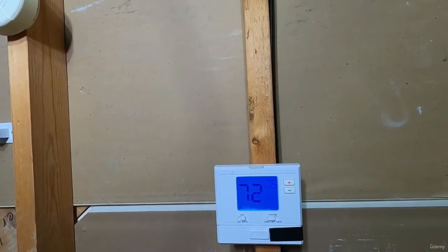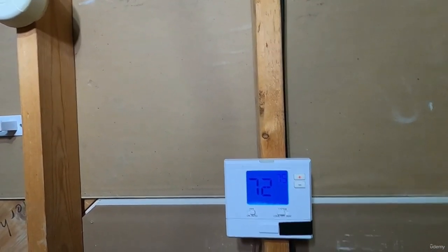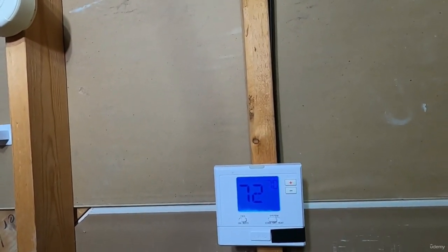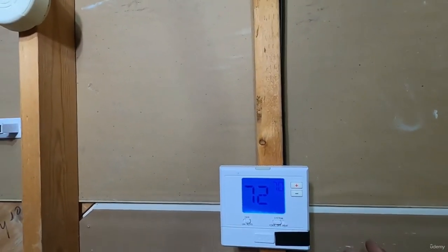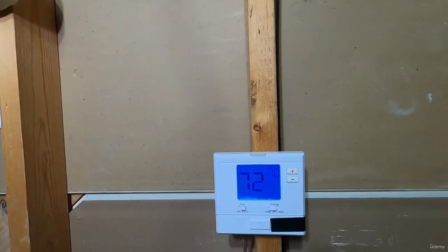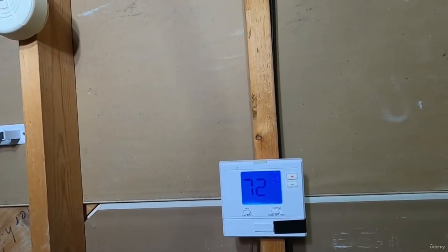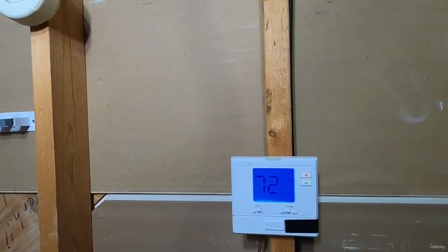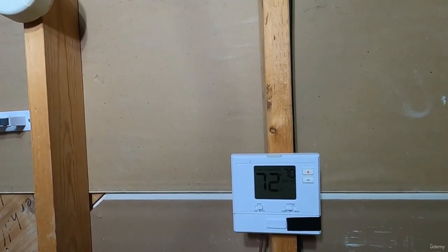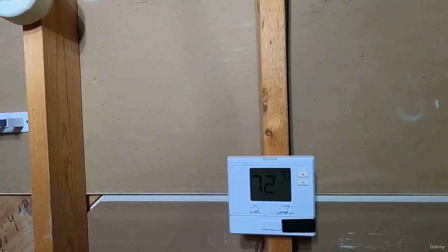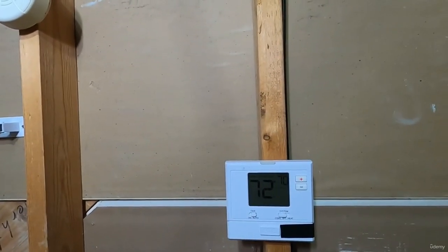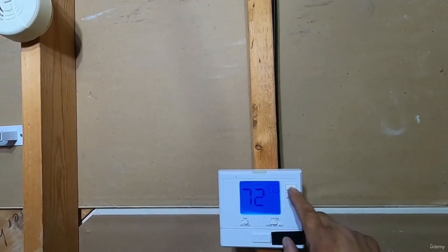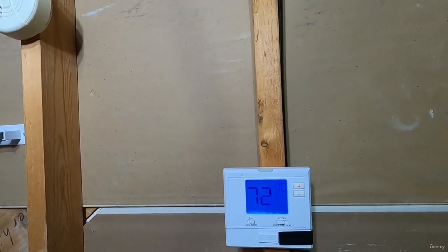Now, also just keep in mind something you may not know. If you turn the temperature up, and then you decide, you know what, I do want it down, or if you turn it off and back on, then it's going to go through typically a 5-minute time delay. Do you see how the cool on is flashing? It won't let you turn the AC off and then right back on. That's kind of dangerous for the air conditioner outside, the compressor. So it goes through like a 5-minute, 7-minute time delay. And after that time, then the cool on will stop flashing, and your air conditioning system will come on.